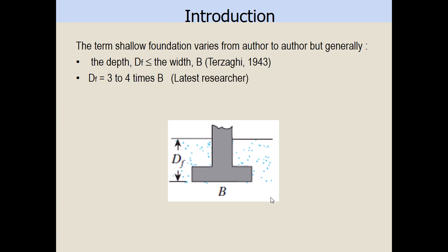Okay, so what is shallow foundation? How to classify the shallow foundation? The term shallow foundation varies from author to author, but generally you can use these notes. The depth from the ground surface to the base of the foundation, this is the Df, should be less than the width. This is from Terzaghi, 1943.